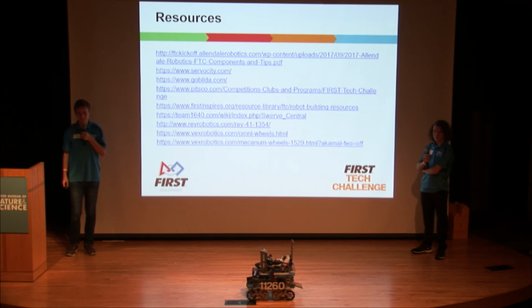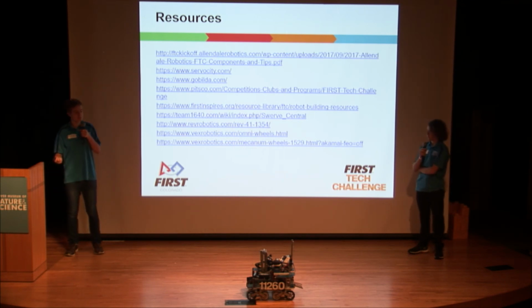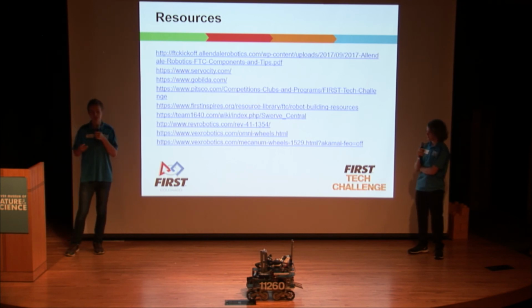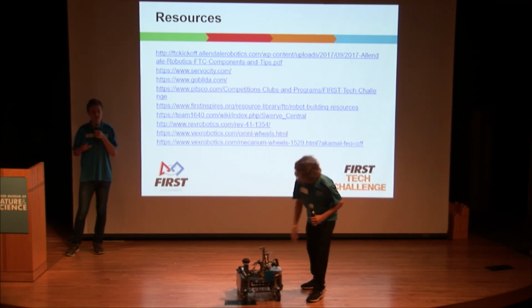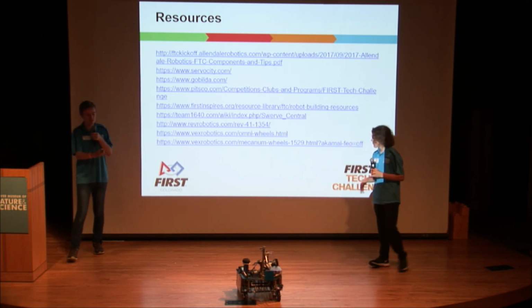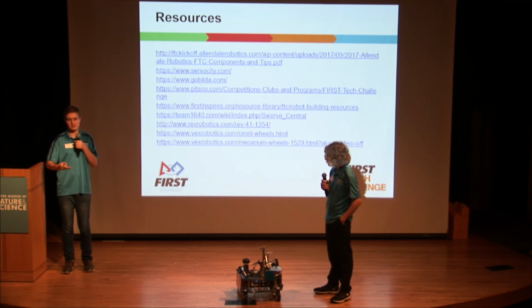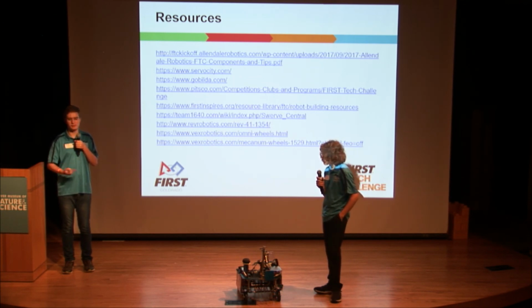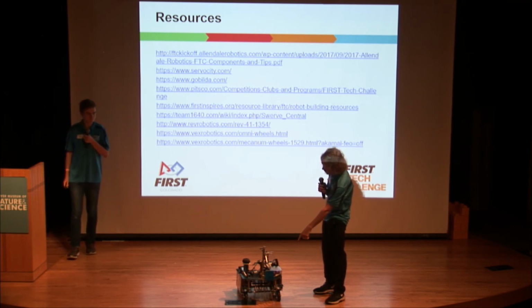What do you mean by intake? I keep hearing that term today. Intake was using an intake brush system as a way of gathering game scoring elements into your robot, and it was very common last year. Like ours, we have a brush intake where rods with brushes on them will spin and push the minerals from last year into our robot, into a holding mechanism. As you see, this takes up a lot of the real estate on the front of our robot.